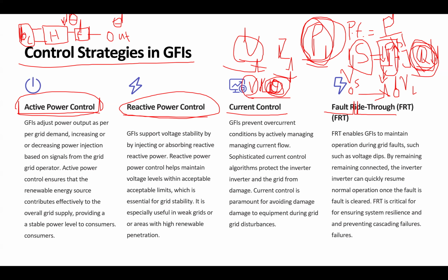I'm going to give you the answer because I don't want to bug you so much. The difference between these two thetas follows Ohm's law. The theta difference represents the impedance. So if you want to model this block, you could consider a dynamic impedance here that controls theta, changing the impedance to change theta to inject the optimized amount of power at your output.